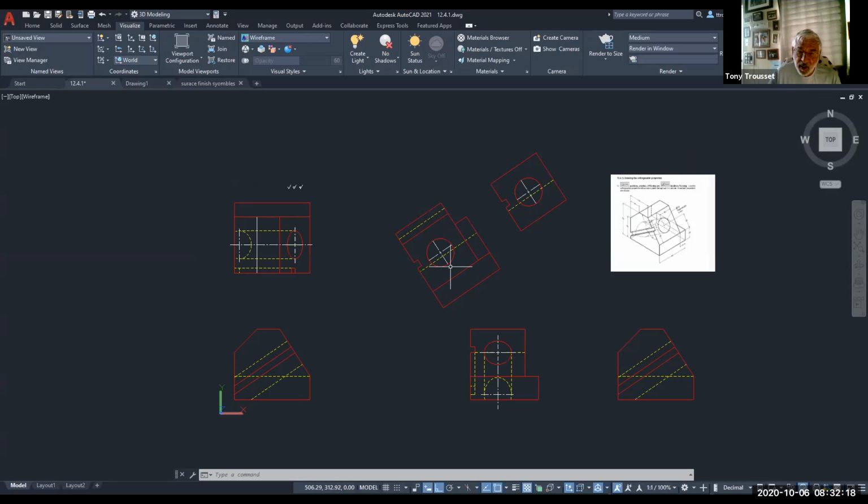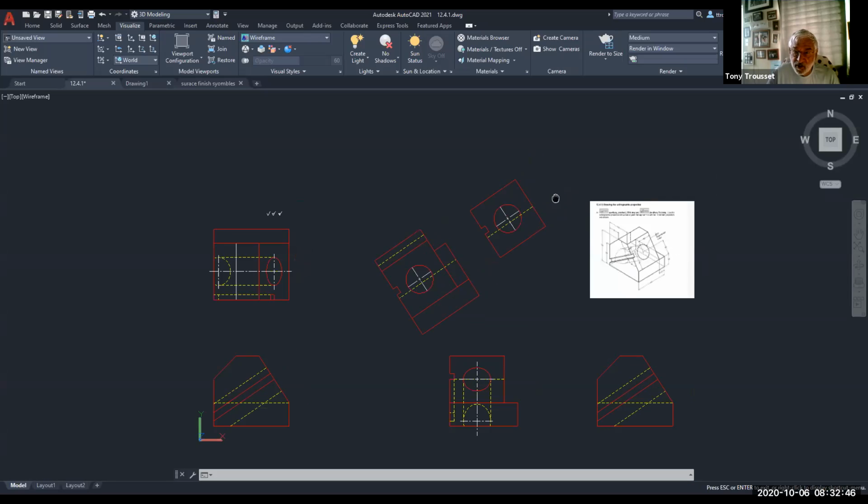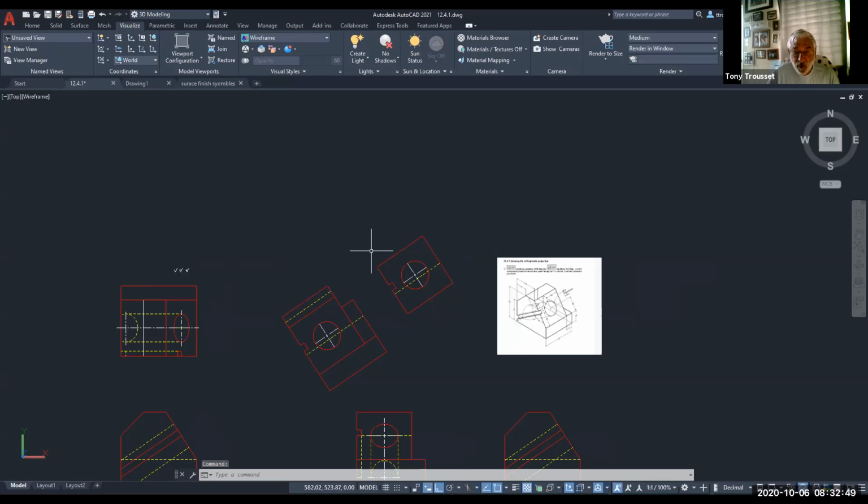the auxiliary view here. When you draw the auxiliary view, I'm missing the oval back here, and I could put a lot more hidden lines in. Well, that's confusing, and that's not the important part. The important part is just this area, here, here, here, and here. So what I did is I took it one more step, and I did a partial auxiliary view. And then at that point, I can dimension it.